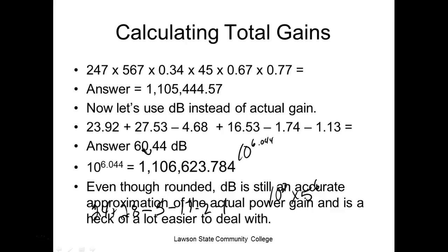So basically, it's a lot like we use engineer notation, but unfortunately, guys, this is not what they did, because we adapted this over from voice communication, right? So we started sending voice over these telephone lines, and voice varies in decibels. So when we moved into communications, it just seemed natural, instead of using engineer notation, we just moved into dB.